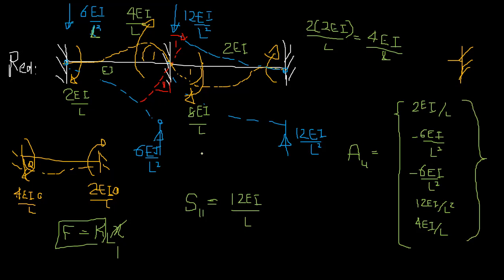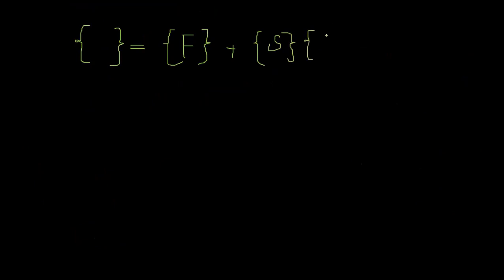So now I need to consider the displacement equation. So I know my force plus stiffness into displacement, right? So I know we are considering the equilibrium. Why? That is what we are taking as the core in displacement method, equilibrium, and in force method, compatibility of shape. So the equilibrium